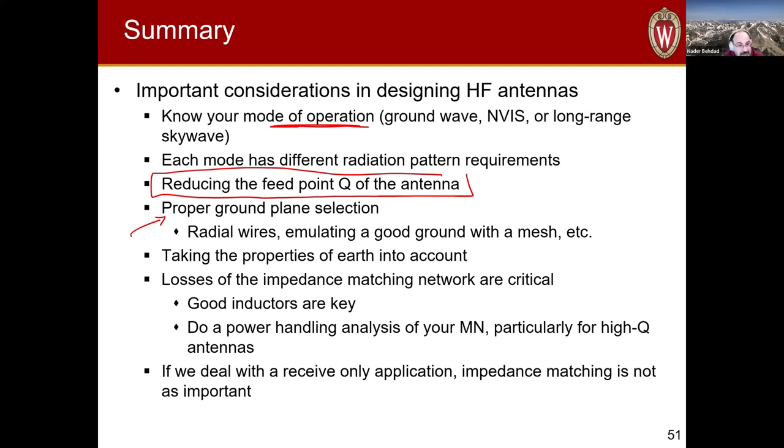But in many situations, this is out of our hands, right? In many situations, especially if you have to put up antennas in the field, you have to work with what you have available. And in those cases, for example, it may come down to using more radial wires in putting up vertically polarized antennas. Whatever you do, if you ignore the properties of the Earth that is in the vicinity of your antenna, you will pay for it. So you have to take that into account.